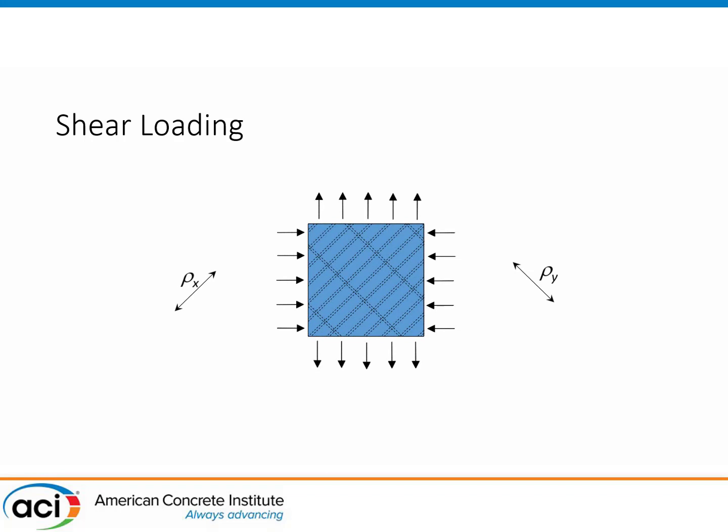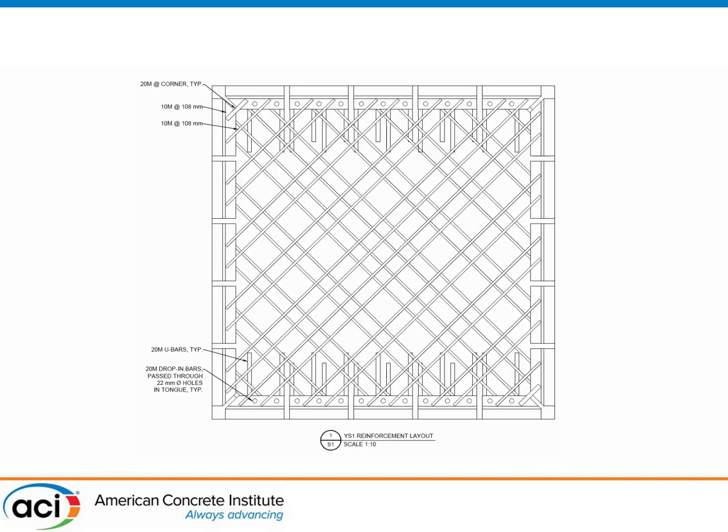So the reinforcement is at an angle, which means that the horizontal forces, vertical and horizontal, provide shear internally. And we found that with regular concrete, this works quite well, very consistent between beam shear tests and the experiments done here as well. It's a measurement basically of what the web is doing without any other components around the outside edge, which is important to understanding the material.